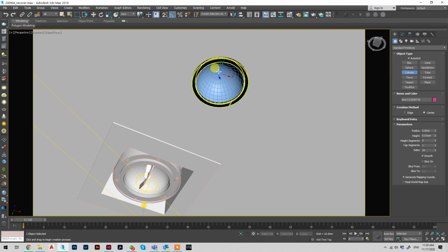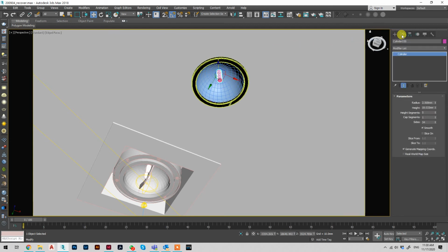So you can add the cylinder, let's say here. Okay, so I'm trying to do this shape that I have, and then I will just take a sphere and make sure that the radius for both are the same, and then they are both aligned together. Okay, so I will go to this part, go to modify, change the height, for example, to 20 and the radius to 2.5.